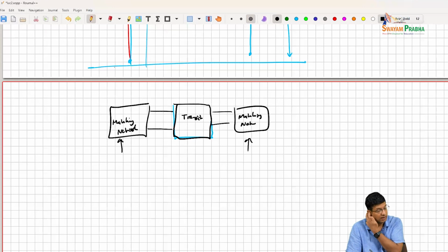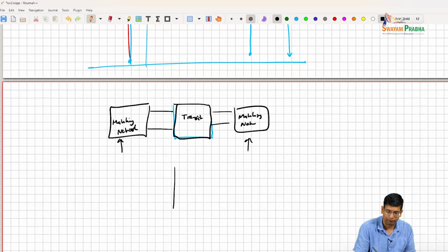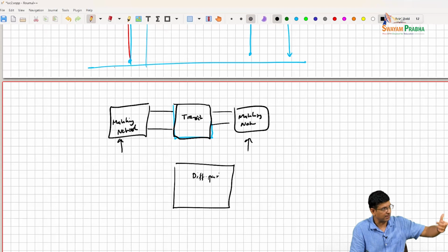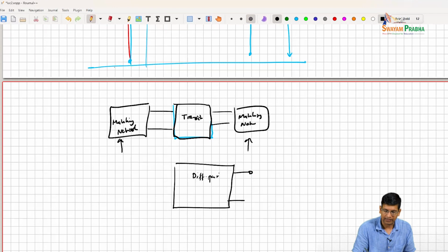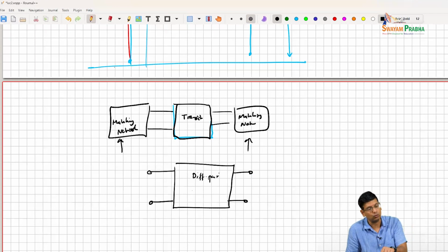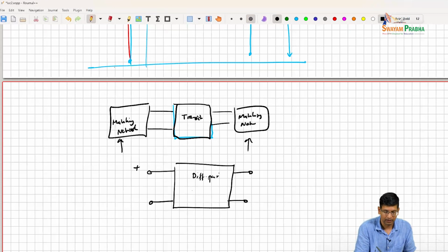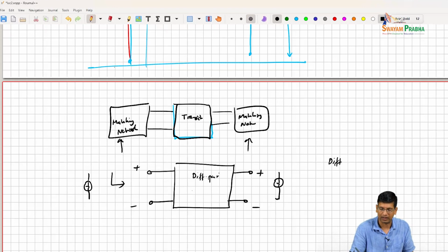That doesn't matter. Now, if you are using a differential pair, right, I can treat the diff pair also as a 2-port input. It's just plus minus ports instead of ground and reference ports. That's a 2-port as well, right? And if you are going to make that 2-port, let's say that I do a differential 1-port here and differential 1-port here, right? And I measure the differential S parameters, right?